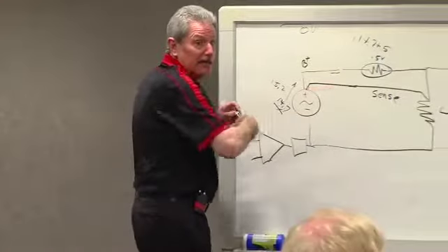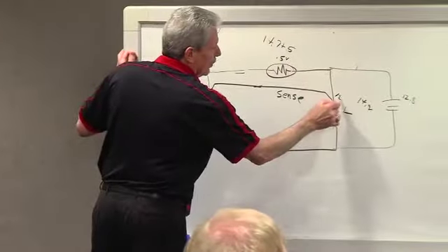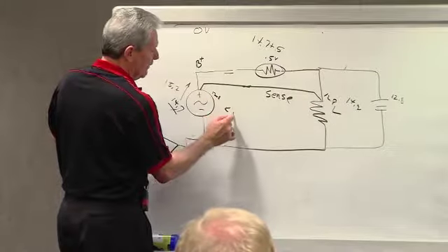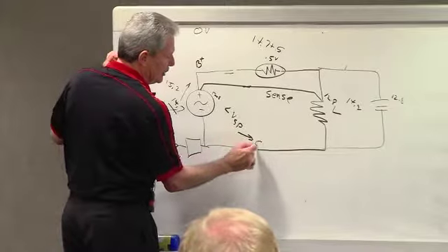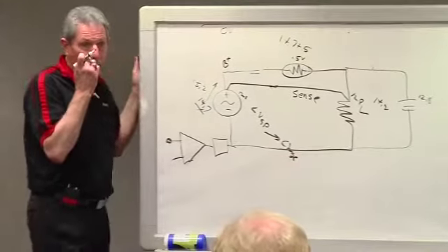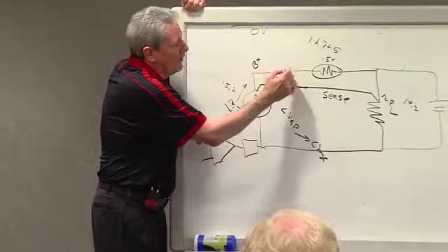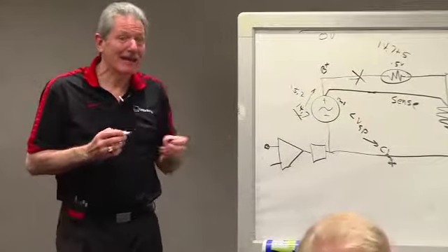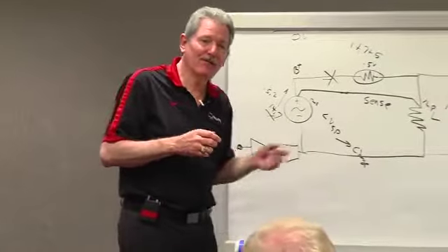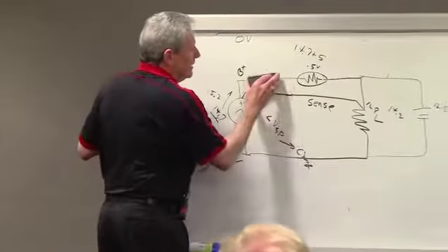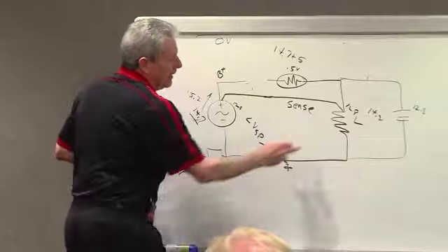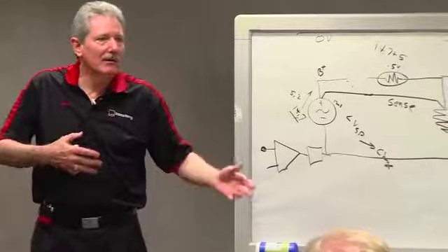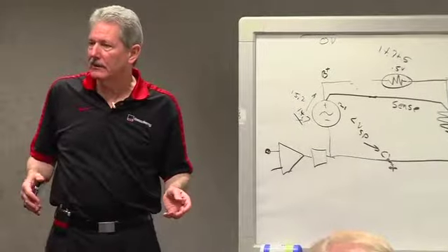The sense line is connected. So the sense line is seeing 12.8, which is below V set point, so it says charge. Because I've opened the loop. That's a bad thing. Now, it's not a bad thing for the vehicle because the vehicle load is not connected, so it's not going to blow your ECU and your clock and the radio and all that stuff.